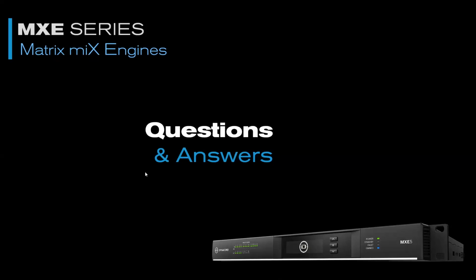Are we recommending a managed switch? So when expanding or adding a second MXE, would you recommend a managed switch? A layer 3 switch makes absolute sense. The reason why it makes sense to have a managed switch is simply that if you're running Dante audio and stuff like that, it makes sense to separate audio traffic from control, because otherwise it gets a little bit flooded. Which, by the way, is the reason we have this control port on the back of the MXE5. This is nothing else but a filtered port that doesn't have the audio, but only the control.